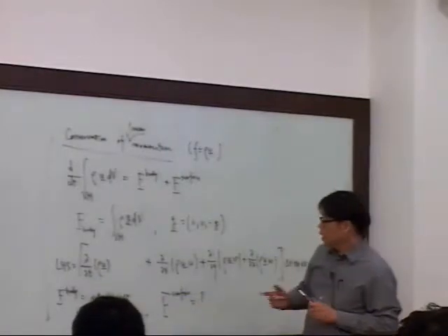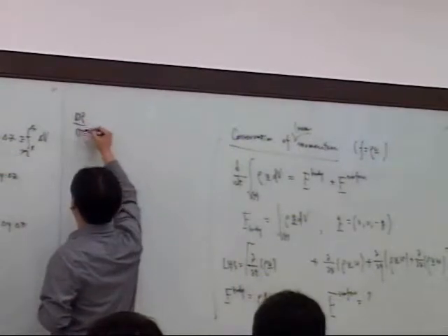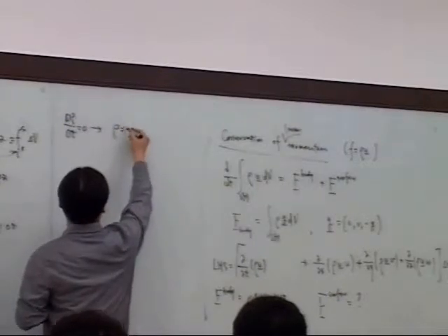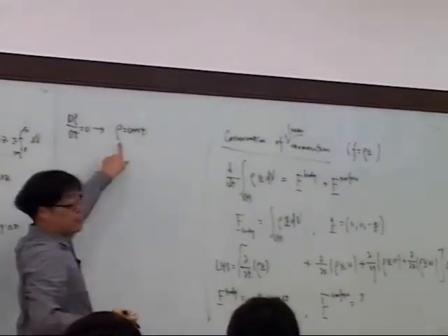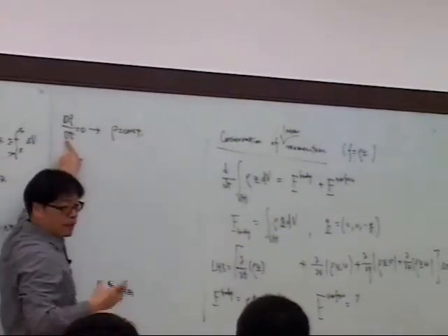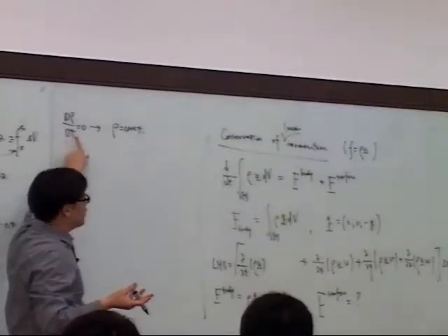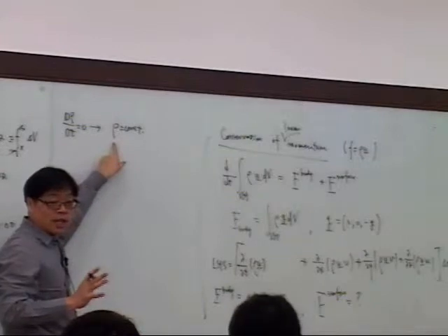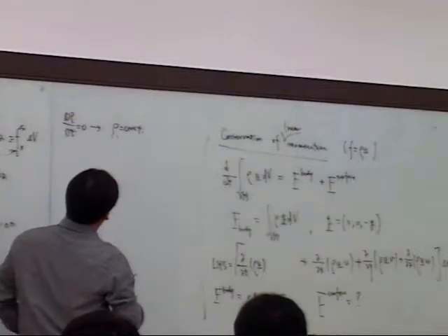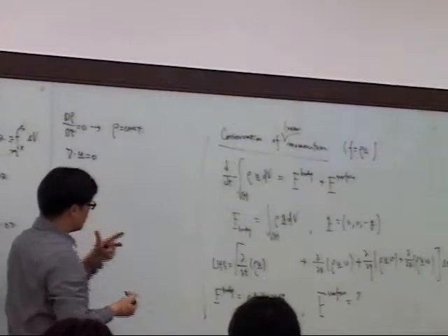And we have d rho dt equal to 0, and one solution is rho is constant, right? This doesn't mean this, okay? Rho can vary in space and time as long as the material derivative is equal to 0. But for this class we assume density is constant, okay? Almost constant, so we assume it's constant. And then we have a continuity equation.